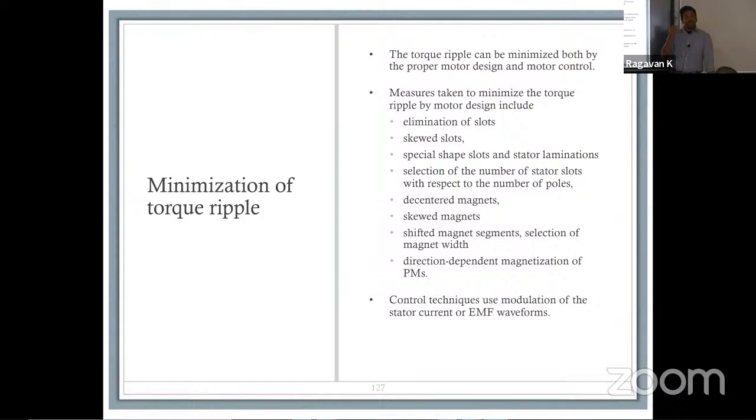For permanent magnets, oftentimes you will see that they also talk about skewing the rotor. So in terms of skew, there is real value in doing that. You can have special shaped slots and stator laminations that are specifically designed to allow you to